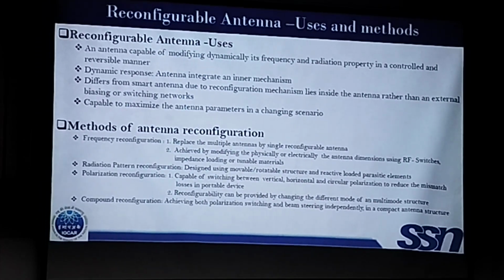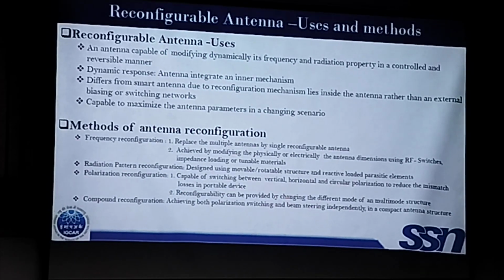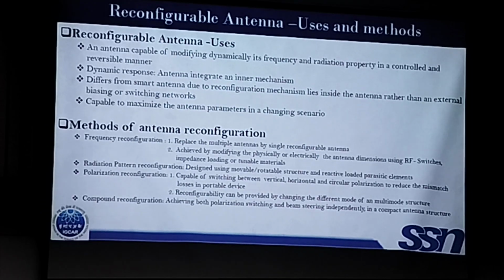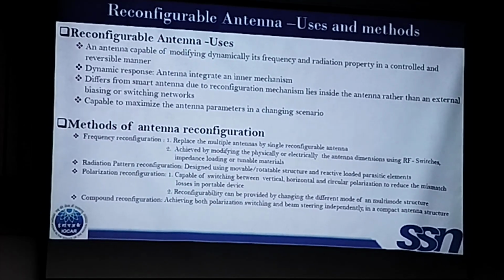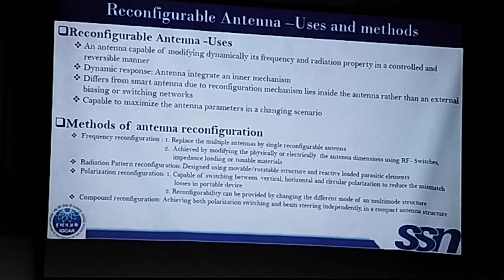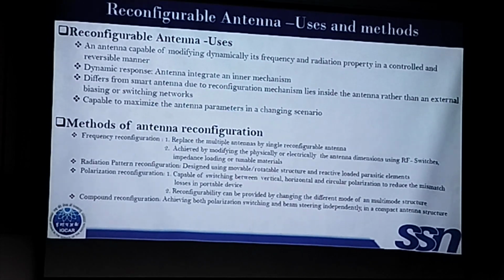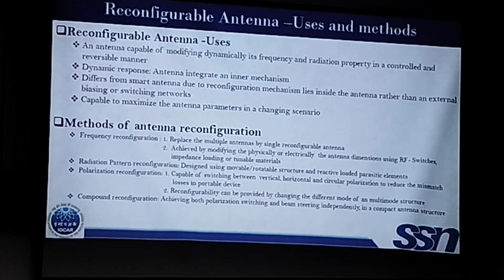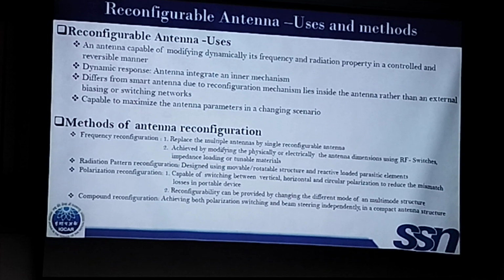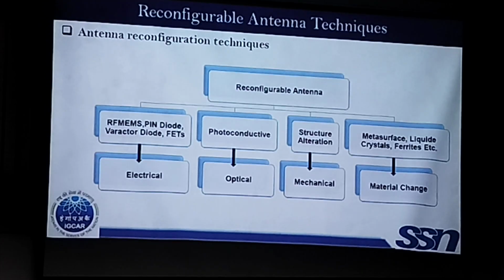So we change the electrical length of the antenna by using the pin diodes. That's how the reconfigurability works in most of the cases. Other than that, we may go for some parasitic directors, parasitic elements included, shorting pins. That's a general case for not only the frequency or bandwidth or pattern. It is for all the reconfigurable antennas.